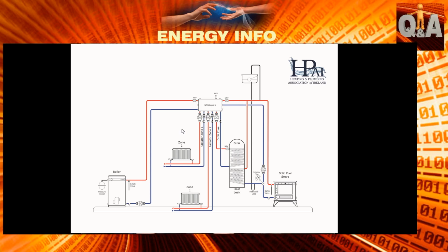Is this setting on the stat, Howie, is that critical? I think it's extremely critical, and because I've always felt that you can't trust the numbers on a stat, what I typically do is turn on the system, light up the fire, turn the stat up to 90 while you're present, stay with the stat, and then when you just can't hold the pipe, a strange fact is you can just about hold 58, 59 degrees. You cannot hold 60 degrees.